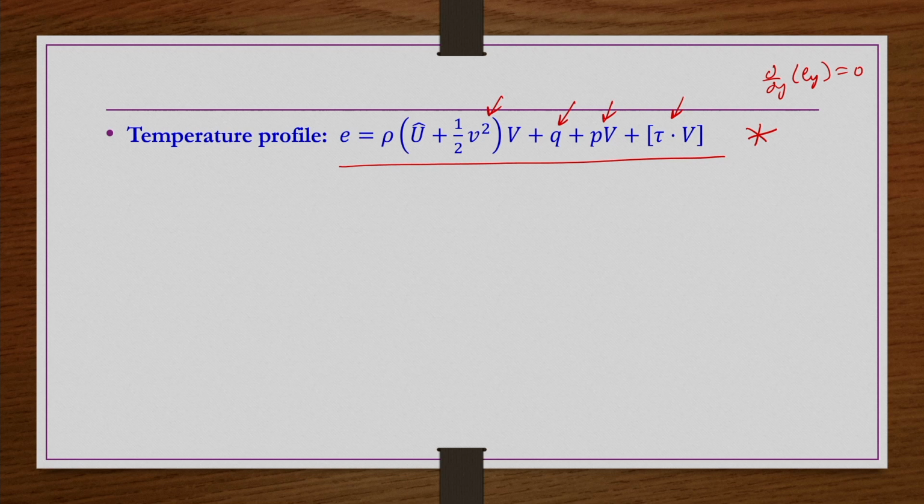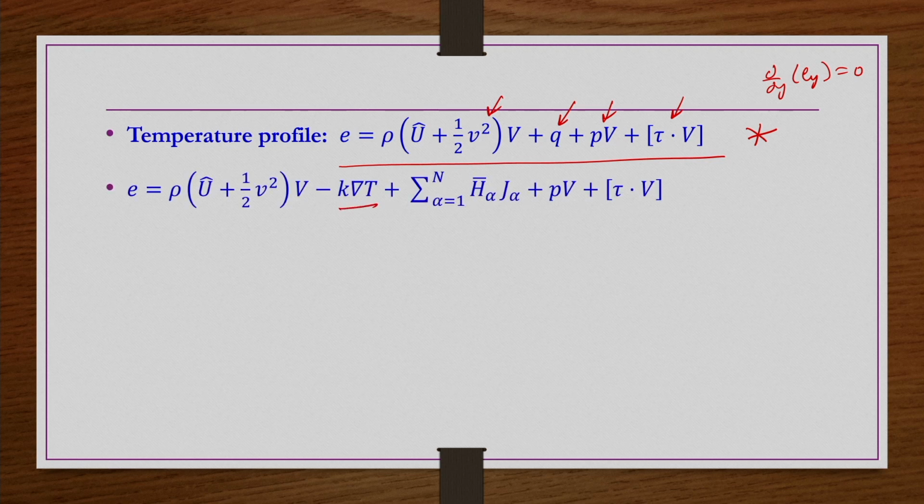Before adding, we will be adding that mass transfer part here, but also we are doing some kind of readjustment, in the sense that this conduction term we are bringing here, and because of the mass transfer the contribution should come in E, that is nothing but sigma H alpha bar J alpha. J alpha is nothing but the molar flux because of the diffusion, and H alpha bar is nothing but the molar enthalpy of component alpha. There are n number of components, right.